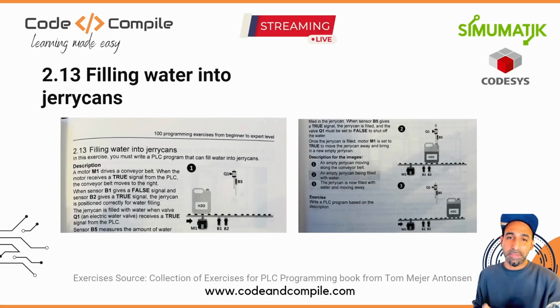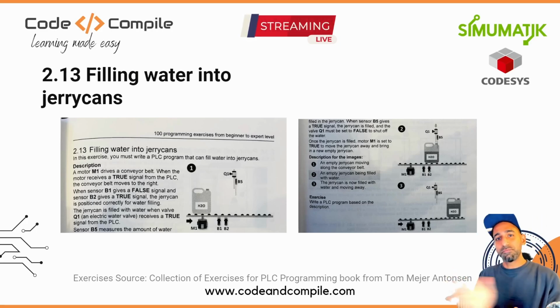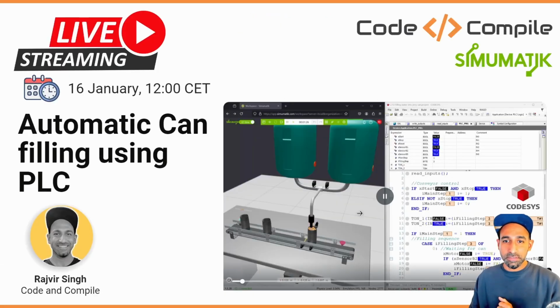So when the sensor B1 is off and B2 is true, it's mentioned here. This means your can is properly positioned. You can see that on this diagram here. And then you start filling it using Q1, and then you have a sensor B5, which will tell you if the can is full or not. When it's full, it moves forward. So actually, it's a very simple exercise, right? And you can see the result of this exercise here.